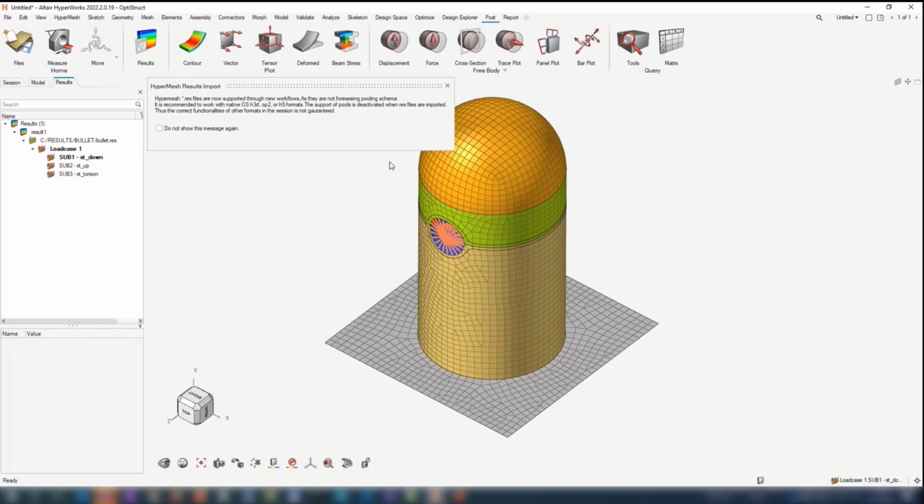For those that are not aware, ID pools mean you may have entities or elements which have the same ID but belong to different pools, and our usual H3D, OP2 and so on support assigning proper results to elements having the same ID but different pools, like shells and solids or beams and MPCs and so on.